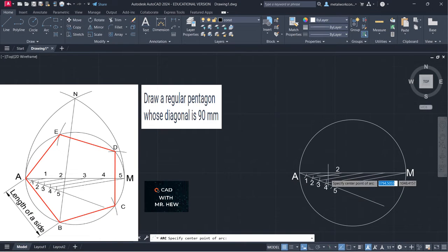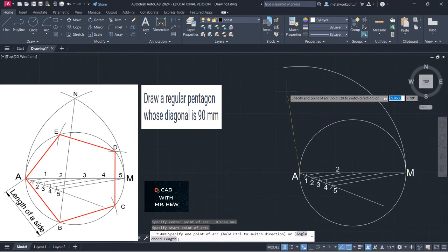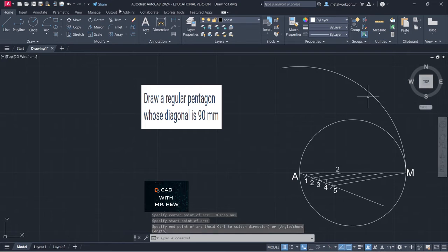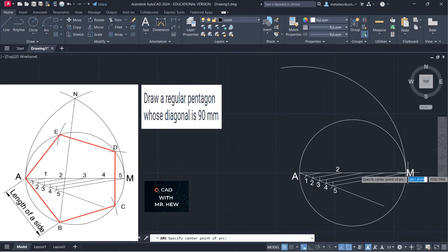So we're gonna turn on object snap because I turned it off not too long ago. We're gonna turn it on. Endpoint. This will be the radius. The radius will be 90, right? I'm gonna come right up like that. Good. So if you have a compass, it's a compass you would have used a while ago if you're using the traditional instruments. So you're gonna go center.